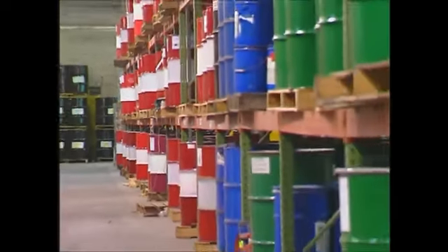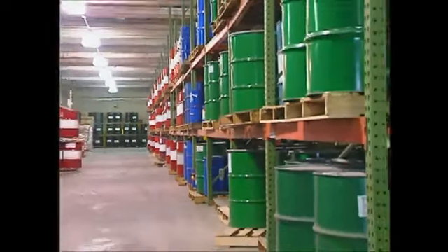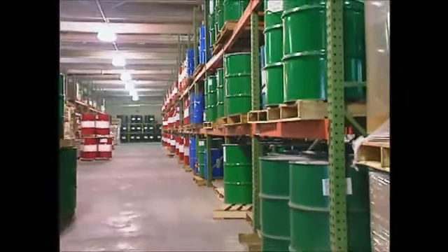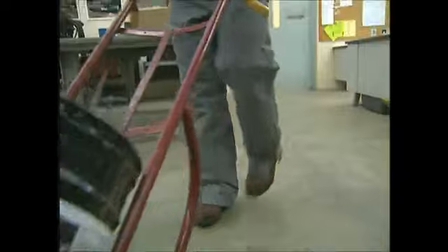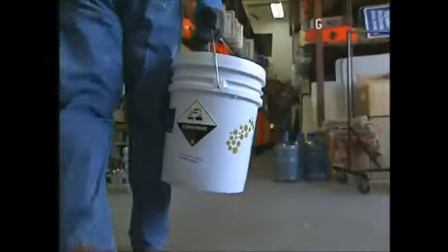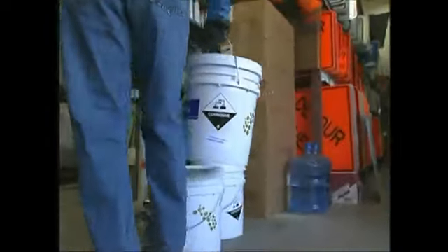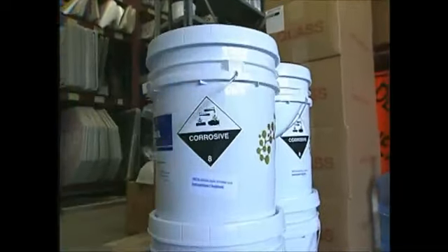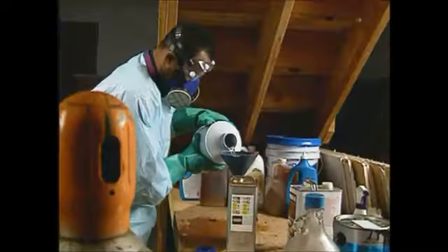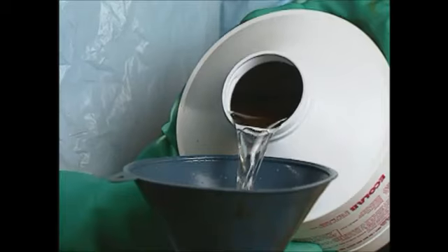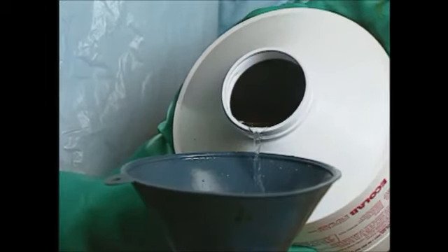You can reduce the risks of hazardous chemicals by using proper handling and storage techniques. While specific requirements vary from one chemical to another, here are some general guidelines that apply to most hazardous materials. Before you use any chemical, make sure you know what it is. Do not use any chemical from an unidentified container. When transferring chemicals, use the proper container for each material. Remember that the container you are transferring the material to must also be properly labeled.